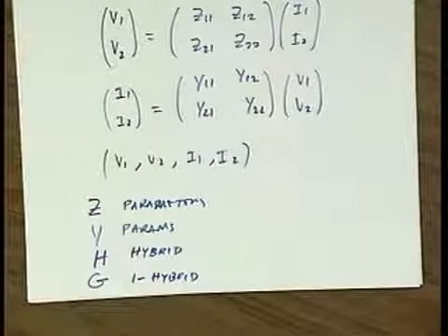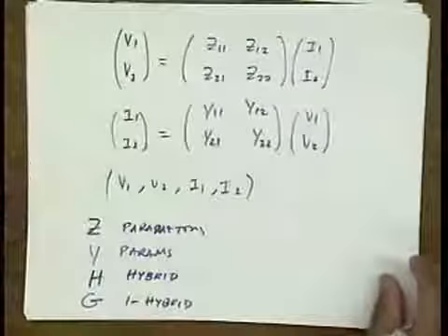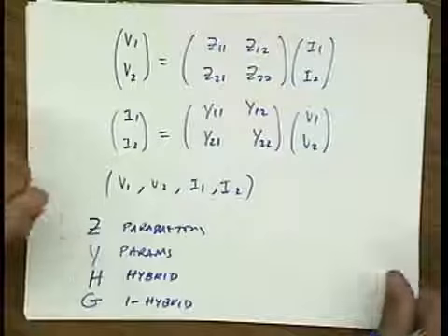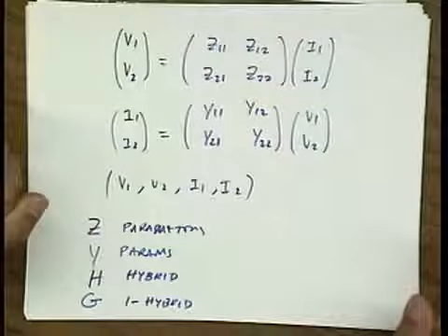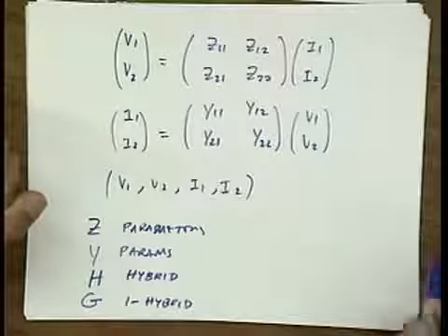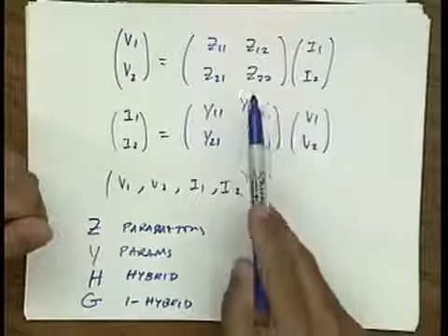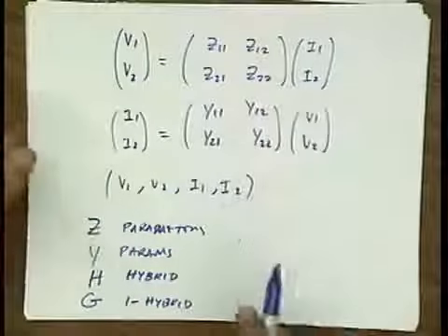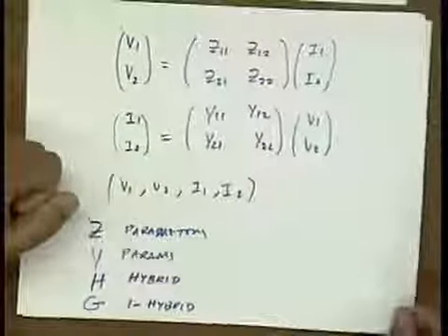Okay, and they're all equivalent. They really are all the same information. So in general, we use the ones that are most convenient for the problem we're solving. You should also note that not all of them necessarily exist. So for instance, you can dream up a circuit that has Z parameters but does not necessarily have Y parameters. That's because we can't invert these relationships.